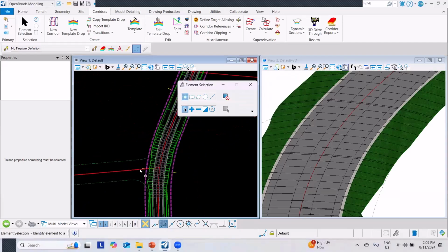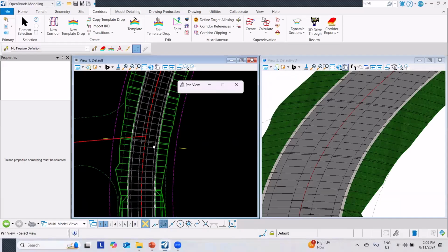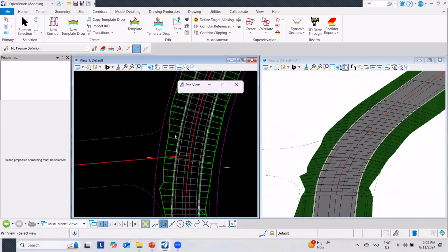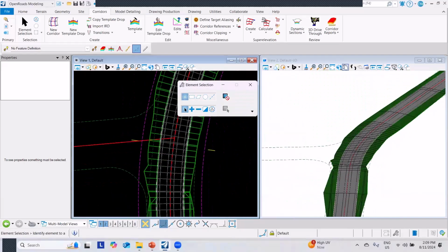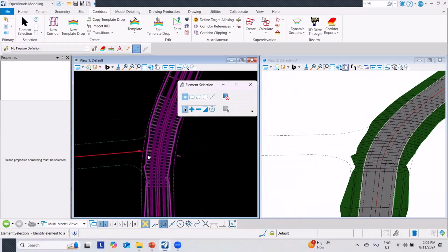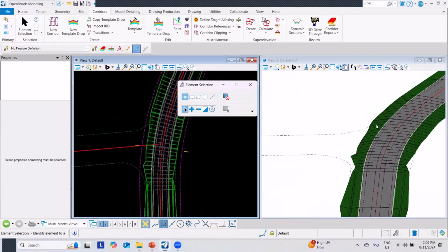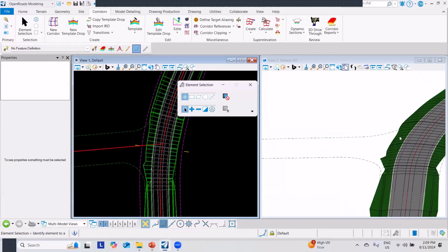So once we are here, we can also identify something over here that we have a road, a secondary road that is connecting our London road. So we need to crop, or we can say we need to cut this particular section out. So what do we need to cut out? We need to remove this particular part where we have the end conditions. We need to remove the shoulder so that this particular alignment that I have gets connected in a very smooth way, right? So that's where we are going to work ahead.